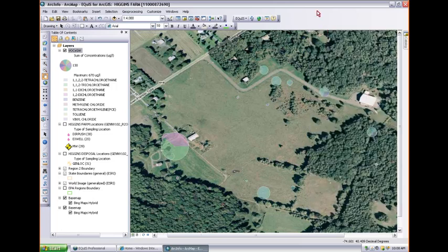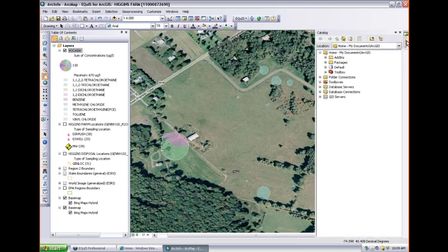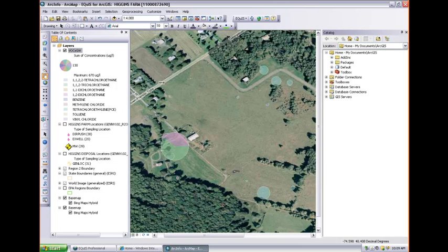I guess while we're going over it, we do take advantage of a couple of ArcGIS 10 features that I should probably point out. They're handy. They have the Arc catalog now integrated. How many people have used ArcMap, ArcGIS? Okay, so the rest of you may not appreciate it so much, but the Arc catalog is now integrated within ArcMap. This is basically what we had to use to manage your data and create any new spatial data files. You had to go out into Arc catalog, then bring it into ArcMap. It's kind of a pain, but now you can do all this within ArcMap.